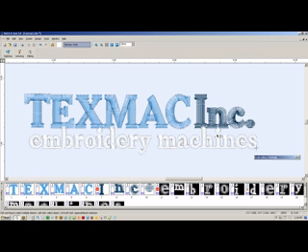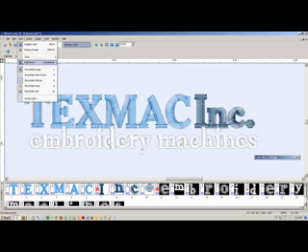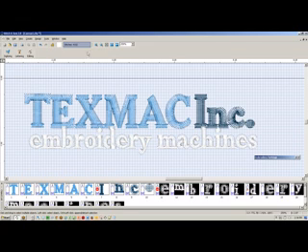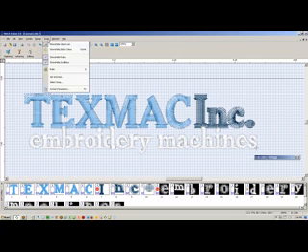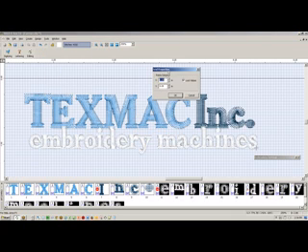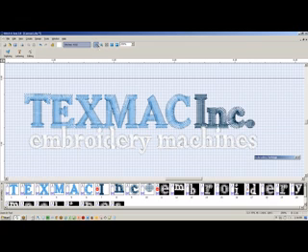Now, what I was getting at to see if the lettering is too small is you go to View and Show and Hide your grid, and you also want to set your grid size, the grid blocks, to the minimum stitch width or length that you can get away with on an embroidery machine, which is about a millimeter. So if you go to Tools, set your grid block size, and make sure that your grid properties, if you're in inches, are at 0.04 inches, which is right around a millimeter, and that's the shortest a stitch can sew.